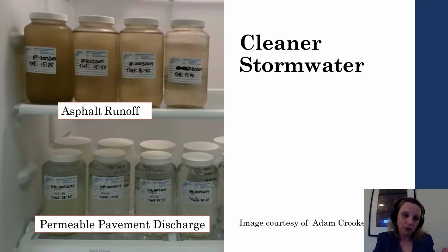The samples were collected in moments in time. The top shelf is runoff from asphalt at that parking lot. And as you can see, we see this effect called the first flush effect, where we have a release of pollutants from all of the dirt and debris that was on that surface that then is mobilized when runoff occurs.